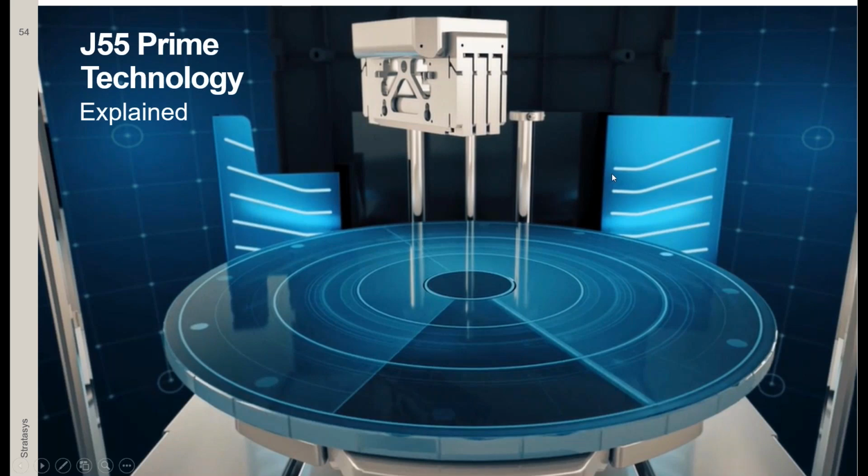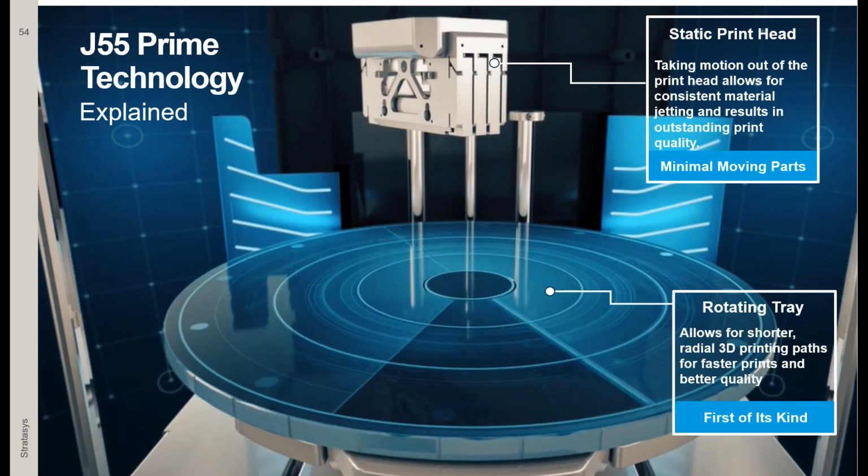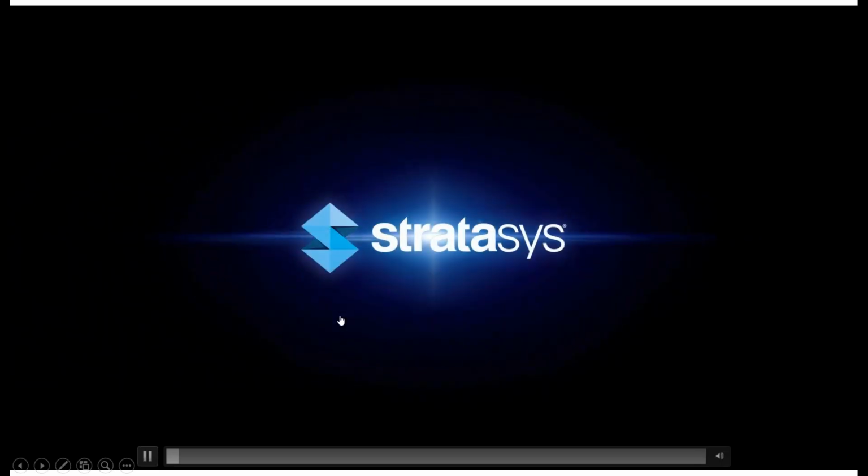A little bit more about how the PolyJet J series J55 Prime technology works. There is a static printhead, and this is a rotary table which keeps revolving around. The static printhead moves in only one direction to cover the entire area, or the cross section, of the build tray, and we call it a swath movement. Here's a small demo of how the system works in principle.